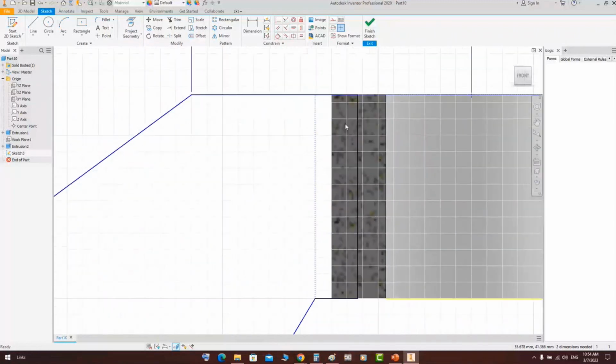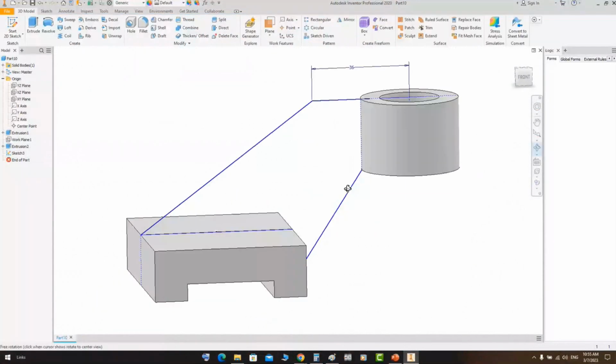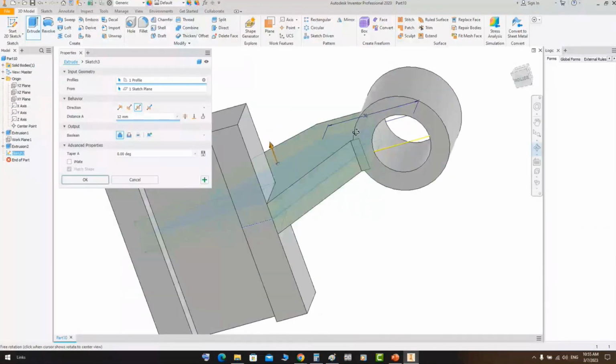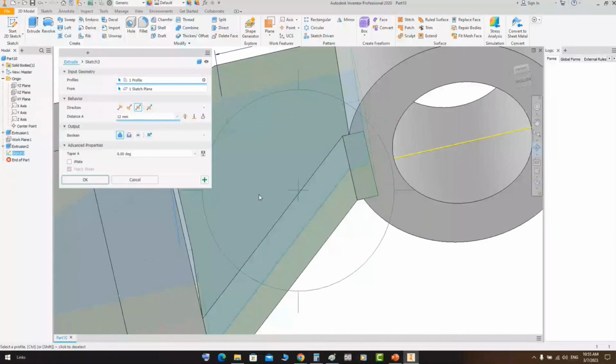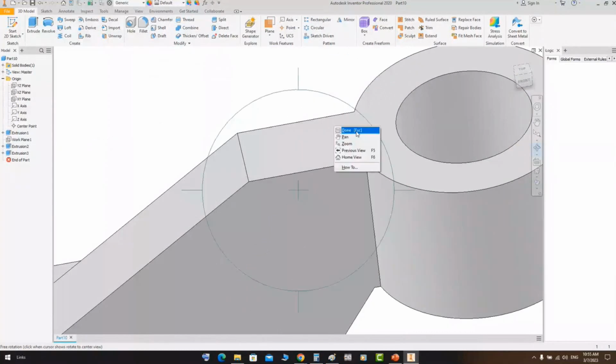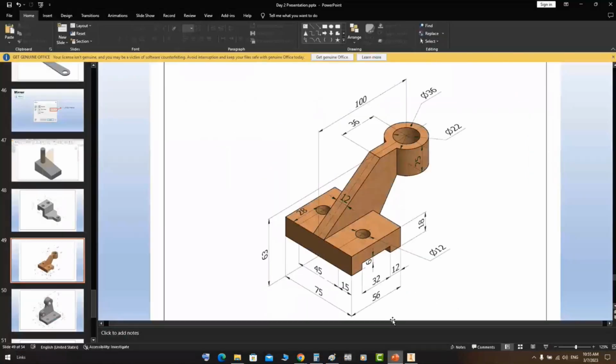So here you make a straight edge on that one. So if you connect this point to that end, let's connect this point to the end here and make a straight edge like that. So when you make an extrude for that one, you will get a good result, which gives you the ability that surface is matching with that one, and that surface matching with that one, and in all the area you have a welded area here, without any gaps. So by that way, we make the 3D model without making holes.